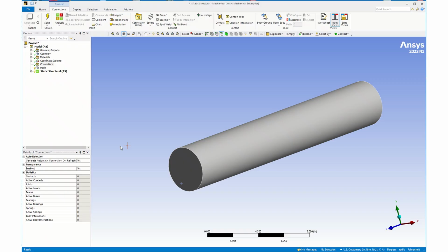In this particular video I am going to show you how to compute the angle of twist in a structure. The same principles can be applied to any structure. In this example I'll simply use a circular torsion bar and compare the solutions to hand calculations. We will also compute the shear stress and the equivalent stress and see how they compare.